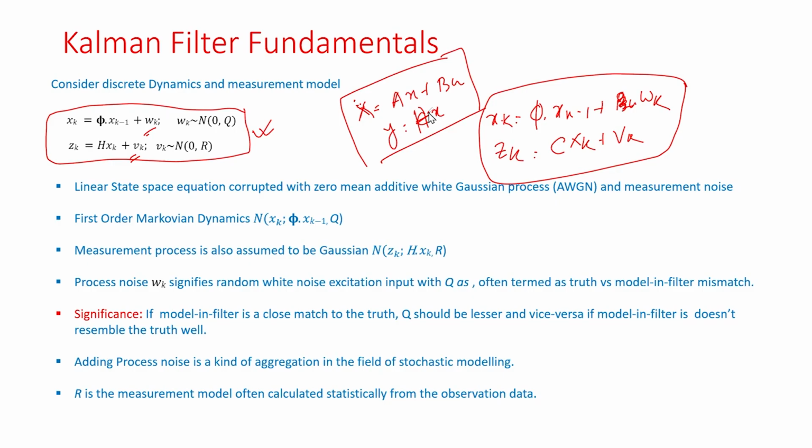You do a continuous to discrete equivalent using some standard transformation like Tustin or bilinear transformation, and we got it. I will tell the transformation when I tell your target dynamics. x_k equals phi of x_(k-1) plus w_k, z equals h of x_k plus v_k. With this, phi is called the state transition matrix, and h is the observation matrix.